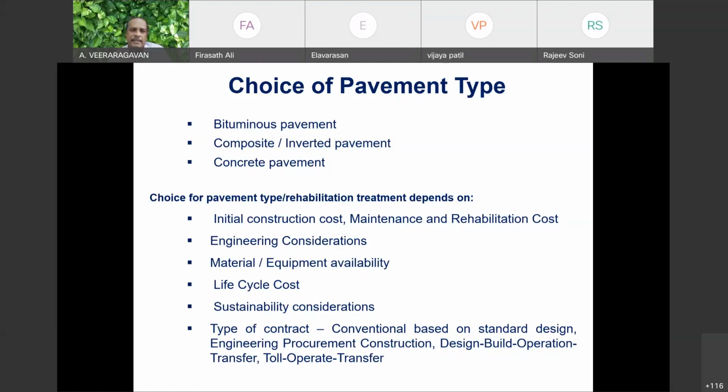That's a conventional design. Then we brought in alternatives: engineering, procurement and construction, EPC contract, wherein you have to do an engineering survey, get the material, construct, and give a longer performance guarantee. Now under public-private partnership, we talk about design, build, finance, operate and transfer. For 20-25 years, you have to maintain the road, which means you will bring better material, better construction equipment, better quality control, you will ensure satisfactory performance. So the risk of design and quantity estimation is not there. It is your funeral. If you want, you can construct with clay. I'm not worried. But you should guarantee me that the roughness will not exceed 2,500 millimeters per kilometer for the last 25 years. So the concessionaire knows that if he spends less initially, he will spend more on maintenance subsequently.